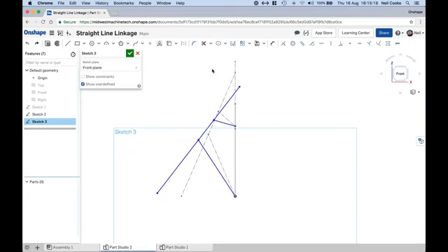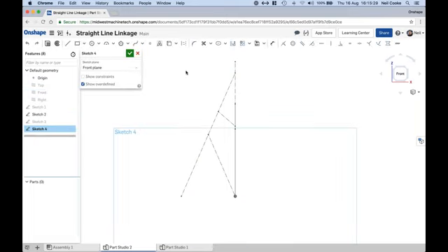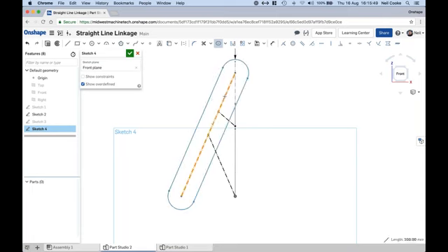In fact, what I'm going to do is build one more sketch just to drive the profiles, and this time it's going to be just one sketch for this, and one for this, because I actually just wanted this to be one continuous line. So this is basically just going to drive my profiles. Then you can use the slot command, for example, to build those profiles that you want to use, and then build the 3D geometry from it.